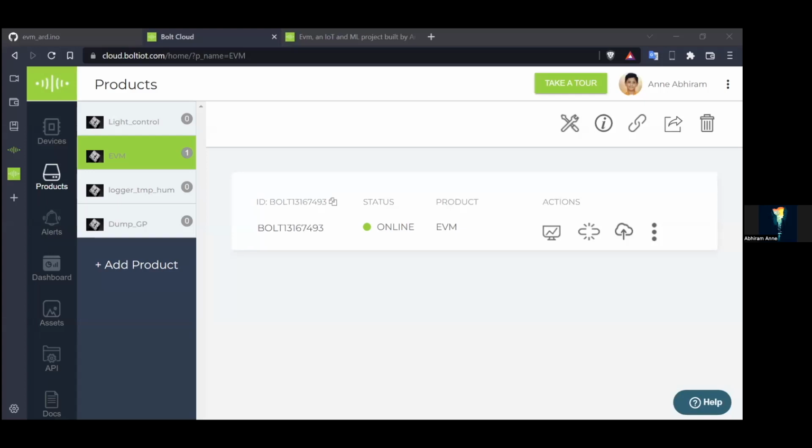There is one question from Omkar. He's asking, sir, in the code, why is there button equals 0? Why not button equals 1? Okay, I'll have to explain this. Coming to the Arduino board, let us say you have not connected any switch. What do you think the logic level would be? It will actually oscillate between ones and zeros.